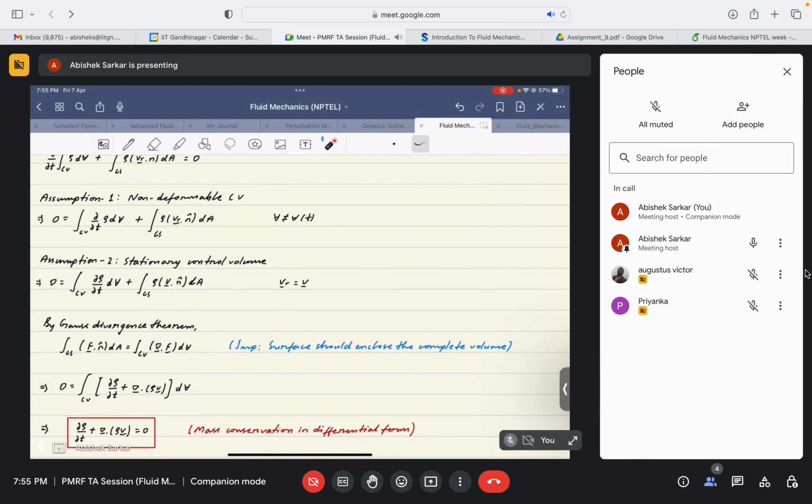So it seems it is clear. This is very important. You will encounter some cases where you have to choose a moving control volume, and then you need to keep in mind which velocity to choose. You might have a velocity that is the intensive property that you are going to conserve, and within the brackets, the inherent term of the RTT, there is a relative velocity instead of the absolute velocity. So whether it is V or V_R, you need to be very sure.